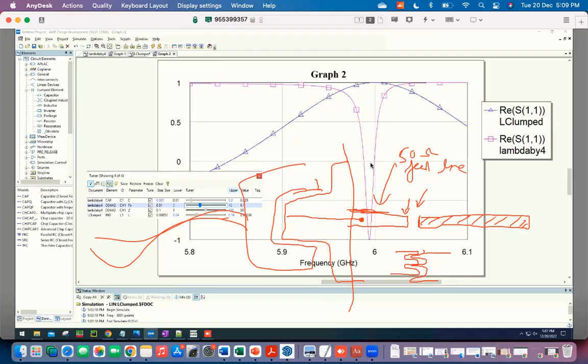What type of capacitance? In these kinds of connections, the only capacitance you can get is between the center pin and ground, not between the pin and the pin. That would be called a bad connection, and you can do that. You can intentionally make a bad connection and you can create a resonator.